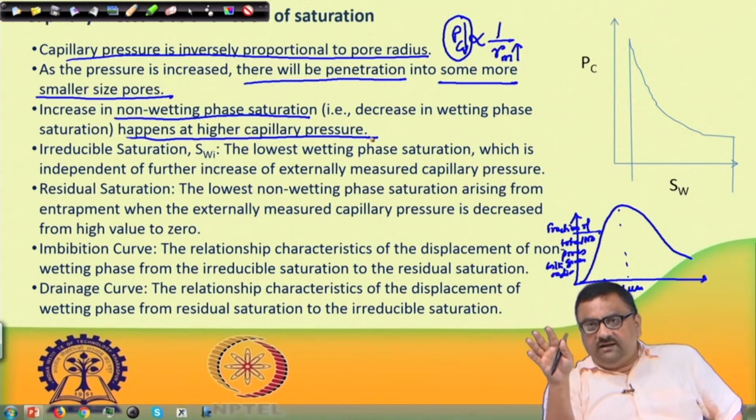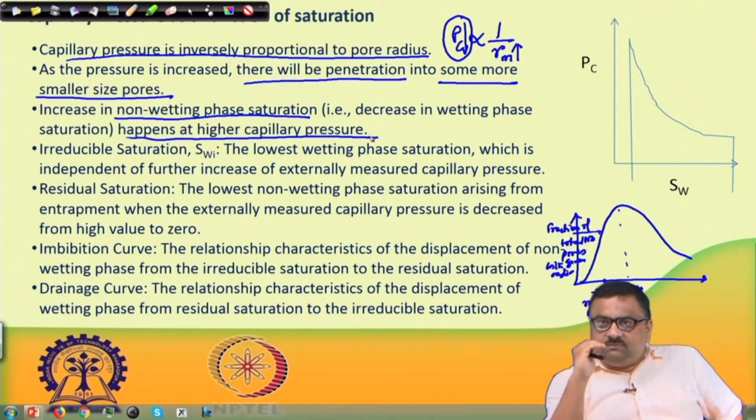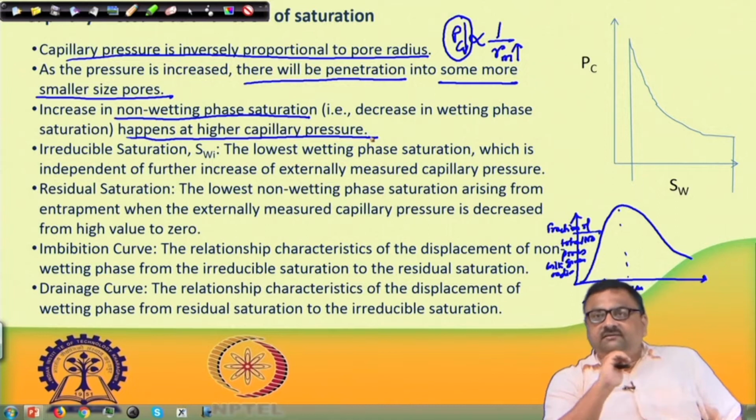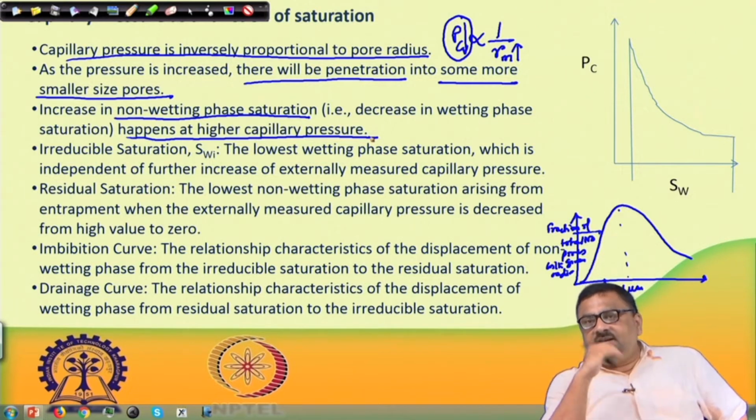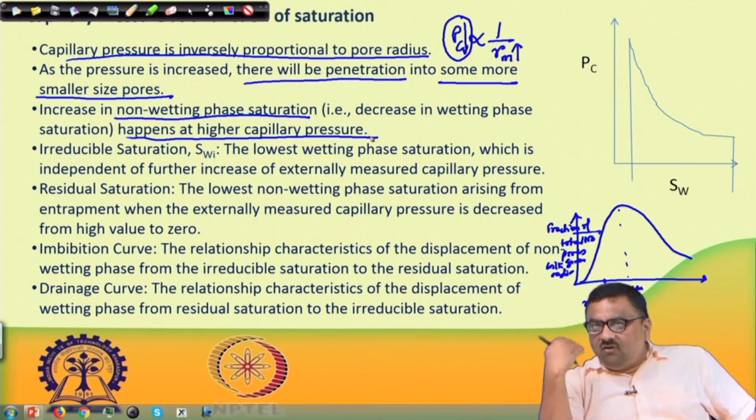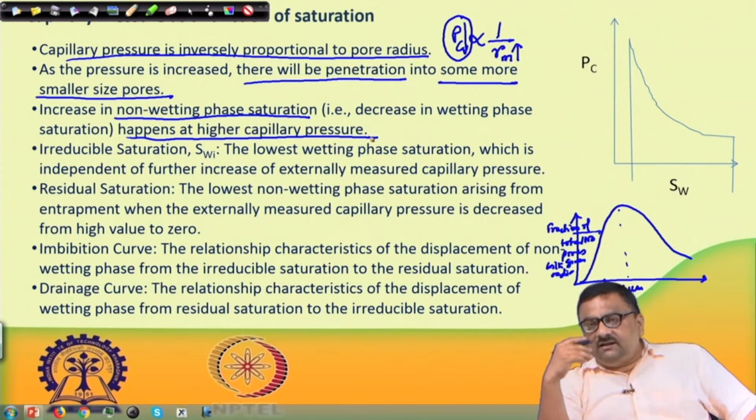So, if we get into this hypothetical situation, then I would expect that as pressure is increased more and more, smaller and smaller pores will be penetrated by oil, and what that means is the oil saturation, that is non-wetting phase saturation, will increase. The porous medium originally contained water only at atmospheric pressure. Nothing happened outside; oil outside, water inside, they will coexist.